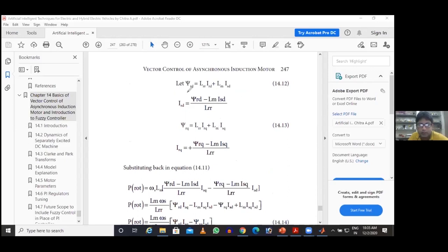So here similarly the rotor direct axis flux is equal to the total rotor inductance, which is also leakage plus mutual, into the rotor direct axis current, plus mutual into the stator direct axis current, which is induced from the stator side. As I told, I want to replace the I_RD. So simply it comes like this. And similarly, I want to replace the I_RQ also.